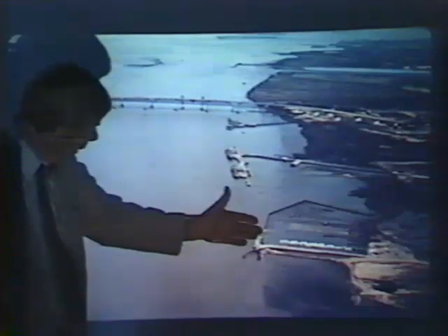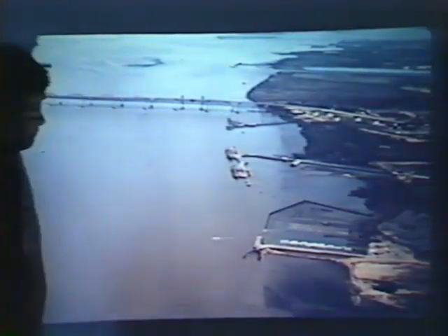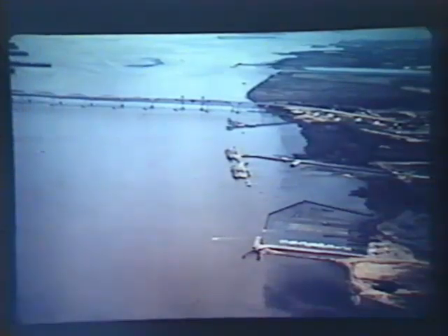And that's another case that I'd like to have had a lot better. They have, averaged over the whole harbor, less than 6 inches a year of sedimentation. But most of it's in the entrance, of course, and everybody goes in and out the entrance. So when it fills up with mud, you have to dredge it. Still, it makes a viable harbor. Economically, it's worked out pretty well. The demand for harbors in the Bay Area is very high, so they can charge enough to keep it open.